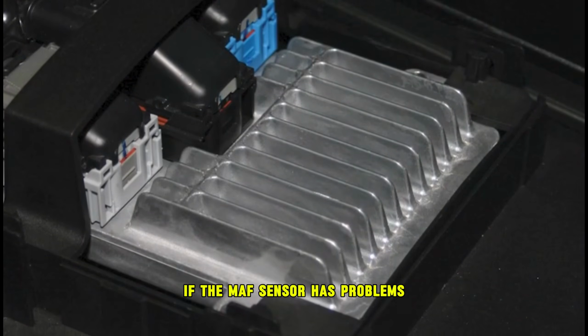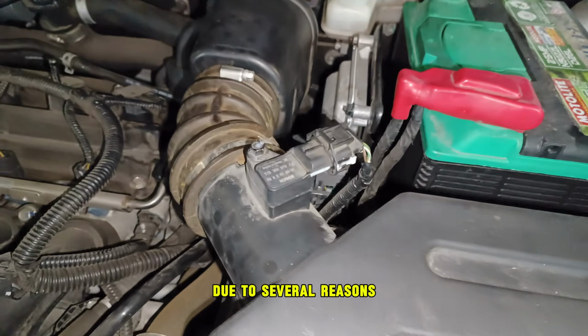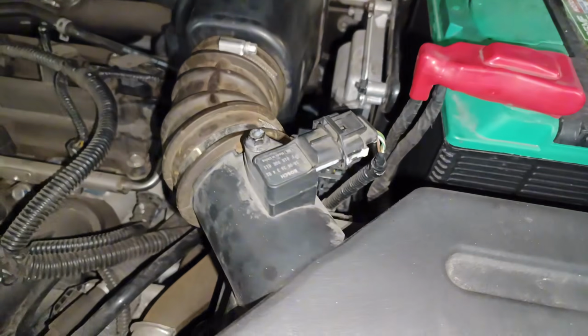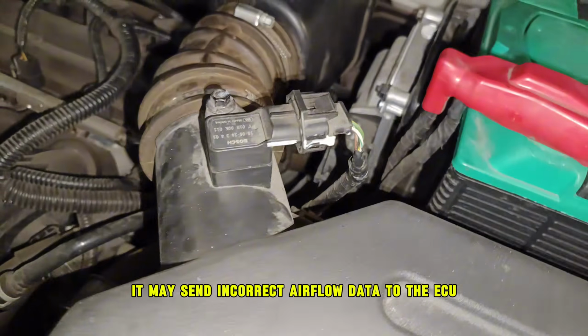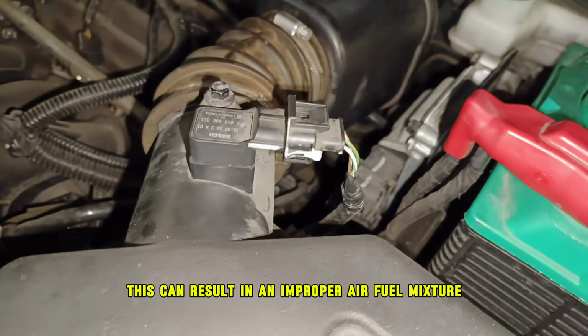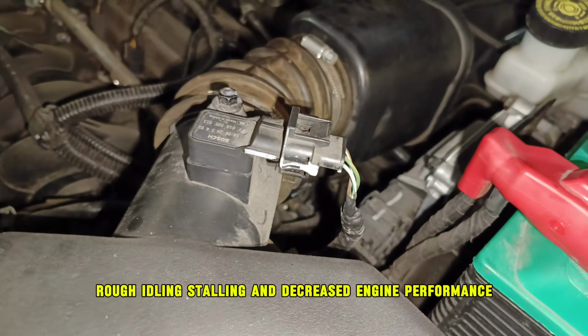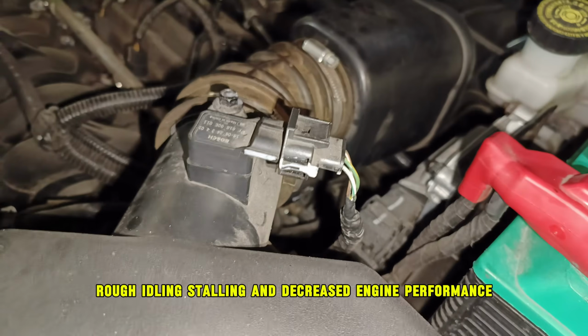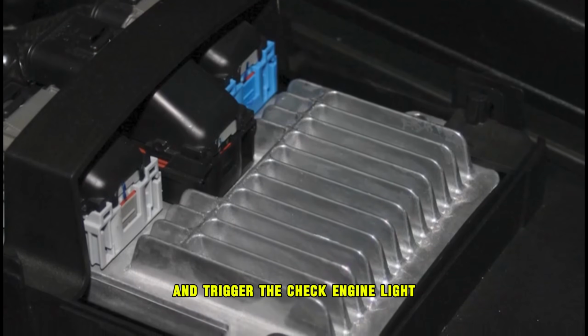If the MAF sensor has problems, it can cause the check engine light to illuminate due to several reasons. If the MAF sensor is faulty or dirty, it may send incorrect airflow data to the ECU. This can result in an improper air-fuel mixture, leading to issues such as poor fuel economy, rough idling, stalling, and decreased engine performance. The ECU can detect these discrepancies and trigger the check engine light.